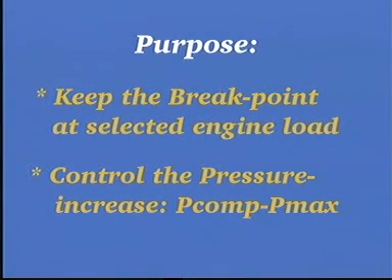The purpose of this adjustment is to keep the brake point at the selected engine load and to control the pressure increase. An excessive pressure increase may lead to a poor cylinder condition. In this event, contact the engine builder before making any adjustment.